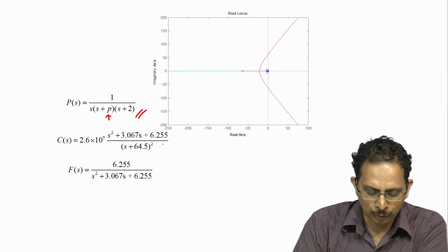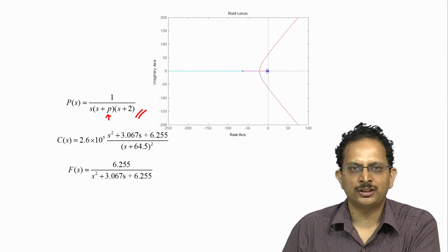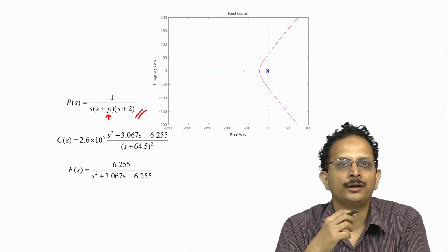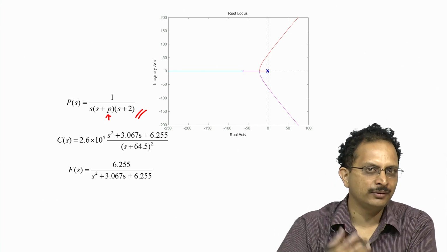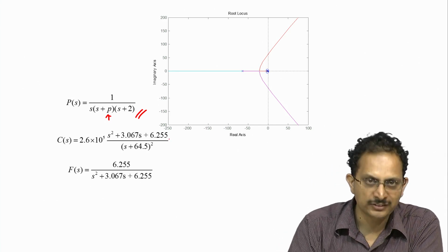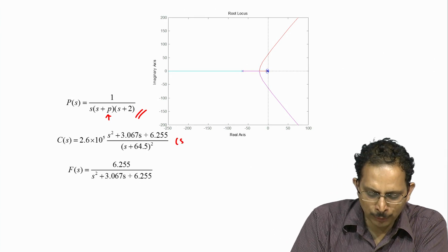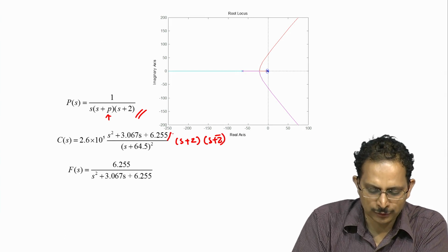The feedback controller would have two zeros z and z bar. The design steps that we just discussed allowed us to determine the distance x of the zero from the point PCL naught, but the angle criterion can be borrowed from the previous clip, and using that we can determine the exact position of the zero z. And if you compute s plus z times s plus z bar, what you get is essentially this expression here.